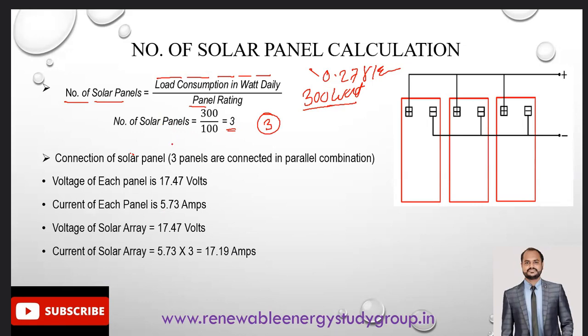There are multiple factors involved whenever we do the string combination in the solar system. If we consider the 3 panels connected in parallel combination, their current value will increase by the corresponding amount, because in any parallel circuit the current increases but the voltage remains the same.